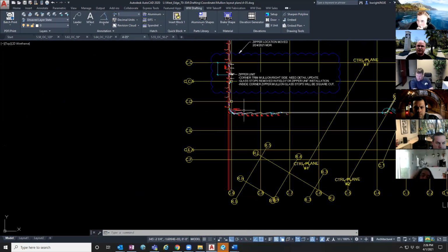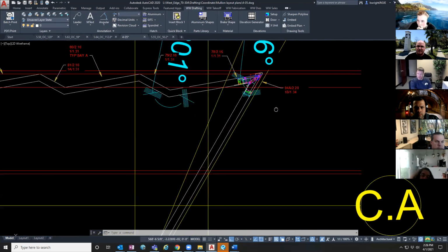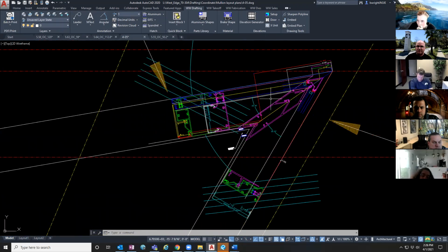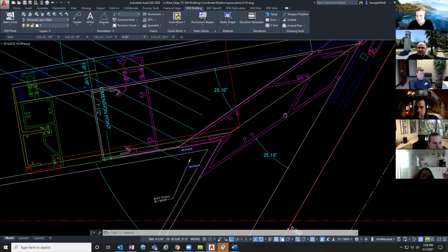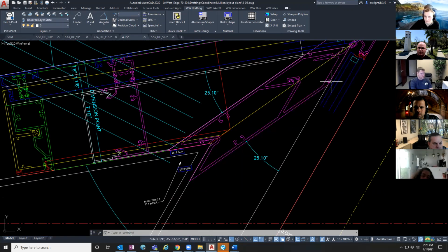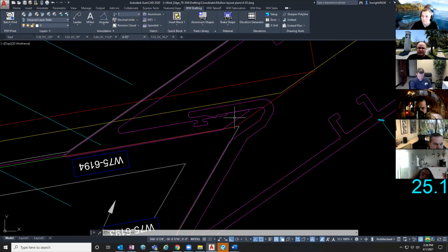So the example that we used, this one, the mullion pairs were built as a 50 degree. So at first we built this as 50 degrees. But when we placed it on here, because this corner is so sharp, we've got such a long surface for this miter that when we rotated it around to match the 50.2 degrees on the floor plan, even though we had originally built this to 50 degrees, it didn't work. These parts of the mullions here were so far out that they would not have closed properly.